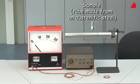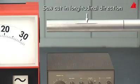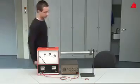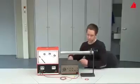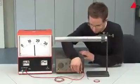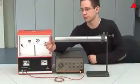Our sample is a tube made from an austenitic non-magnetic steel. We have purposely machined two cuts through the tube wall, one in longitudinal direction and one in circumferential direction. And here we go. The materials tester connects the return cable to the alternating voltage source. This closes the electrical circuit.